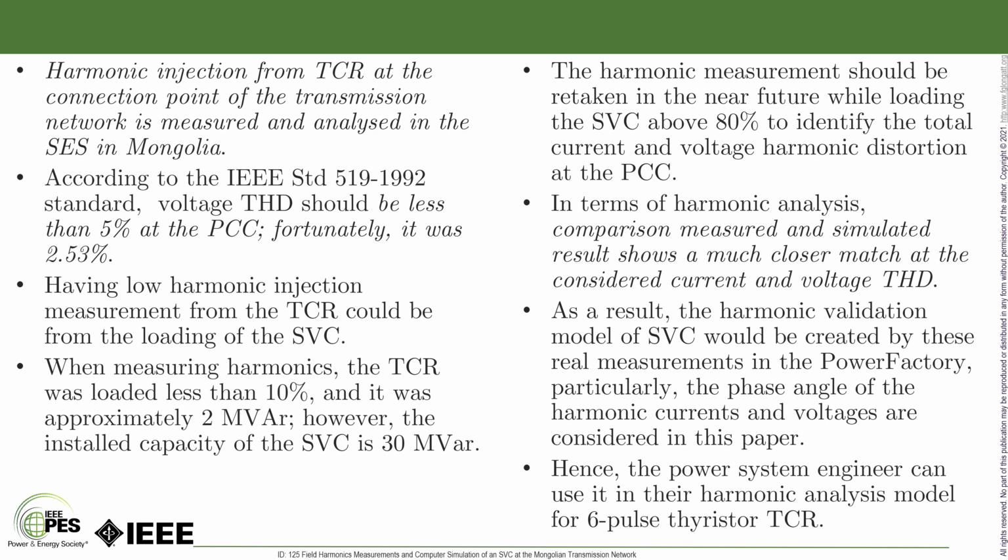Okay. The interesting thing here is that we had the opportunity to take real measurements and then compare with the model that we have inside DIgSILENT PowerFactory and compare the THD, and we got some decent results between the simulation and the real implementation. Finally, it's worth saying that with this paper we can assure the company that in this case the noise was not related to harmonics at this moment. However, a further assessment of that transformer was suggested.